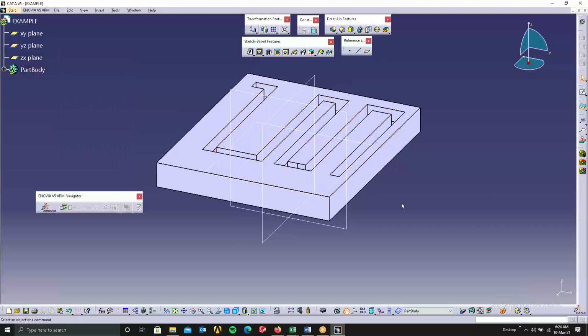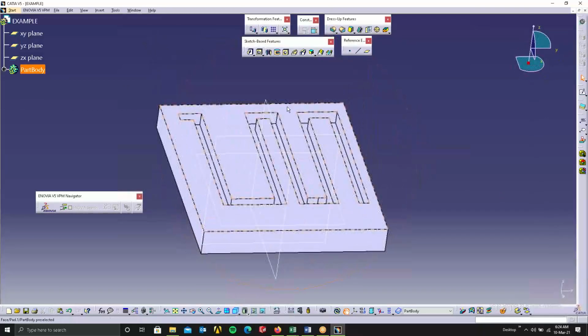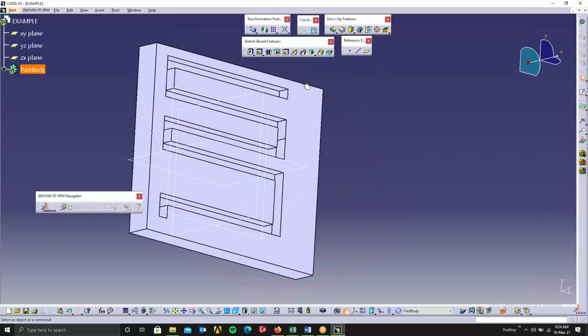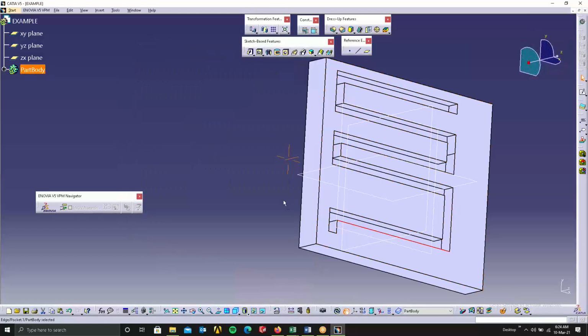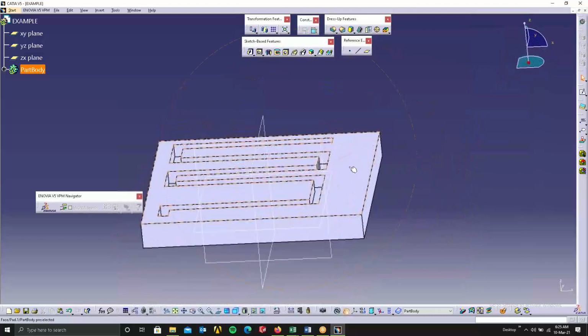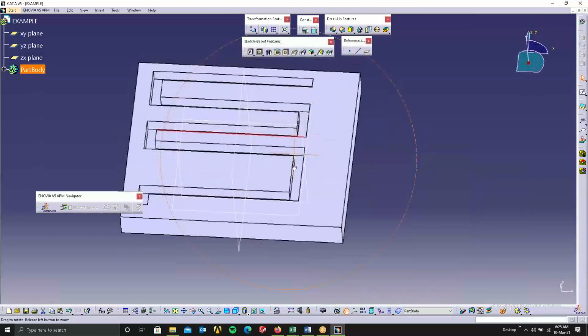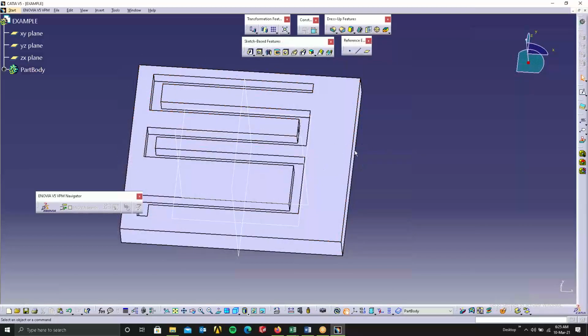I've given the grooves, everything. So this is my cold plate. This is a hot region, so I kept more fins and more grooves in this area. So this is done, right? Are we missing out anything? As a designer, can you just check? Is it all right?